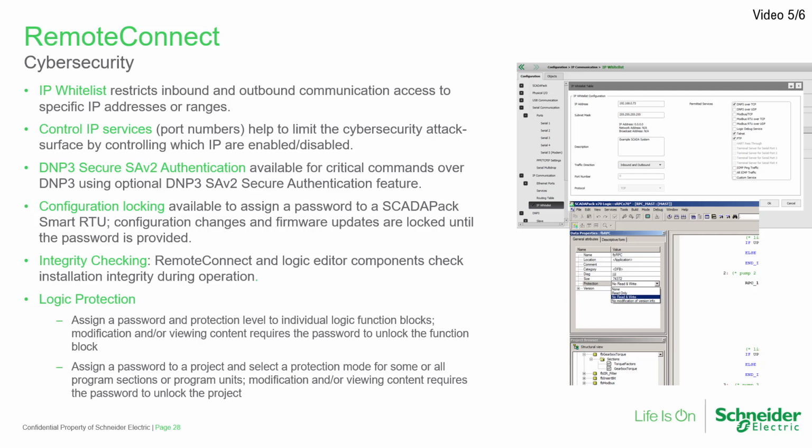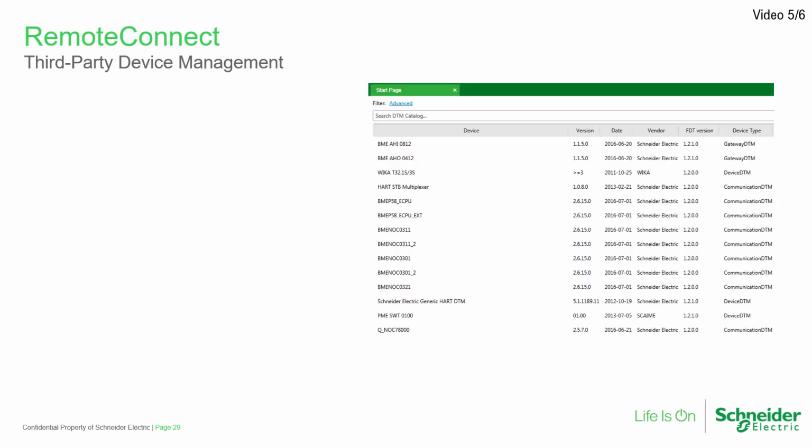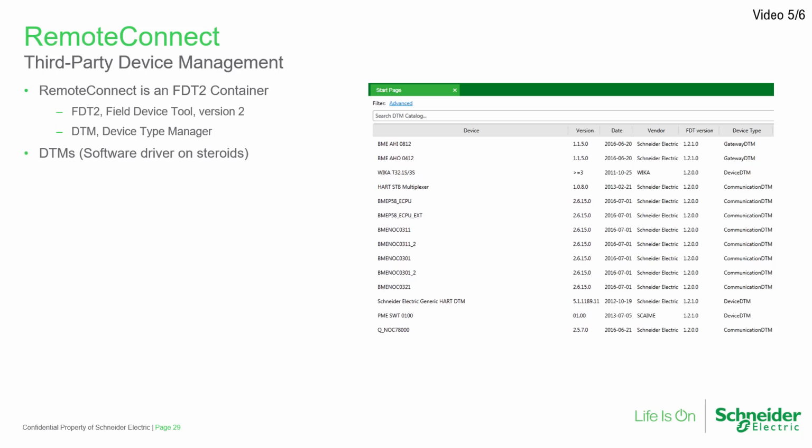Third-party device management is possible with RemoteConnect because it's an FDT2 container, specifically FDT2 Field Device Tool version 2, and the DTM, a device type manager. DTMs can be considered as software drivers on steroids. RemoteConnect accepts plug-in software DTMs of version 2 or version 1.2, and device DTMs are available from instrument vendors. They provide an operator interface for managing and configuring the device.